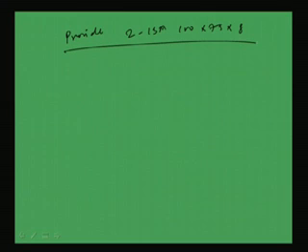So, this is how we can find out the cross sectional property, that is, the required section, in this way. So, finally, what we can say is to provide 2 ISA 100 by 75 by 8 angle. For case A we can provide 2 ISA 100 by 75 by 8 angle.